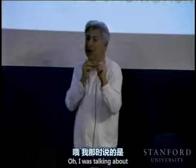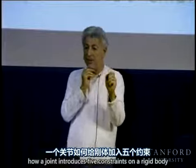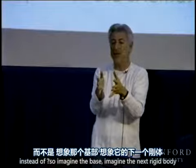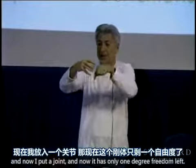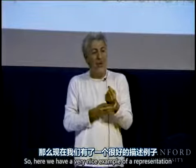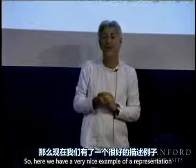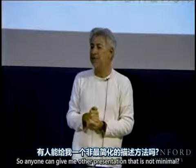I was talking about how a joint introduces 5 constraints on a rigid body. Imagine the base, imagine the next rigid body, it was free completely to move, and now I put a joint, and now it has only 1 degree of freedom left. So here we have a very nice example of a representation that is minimal representation. So can anyone give me a representation that is not minimal?